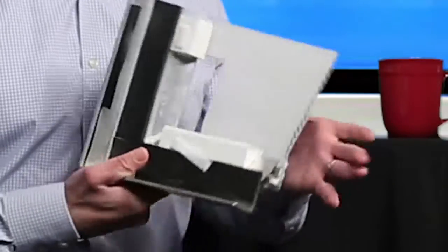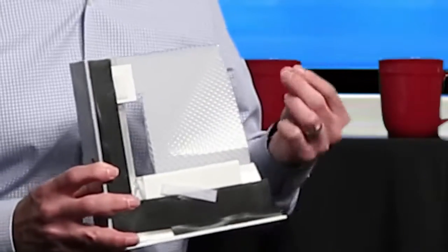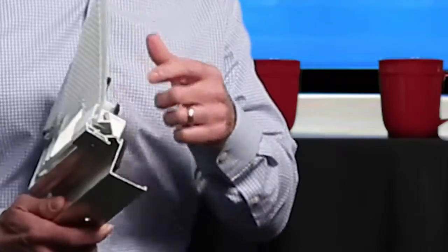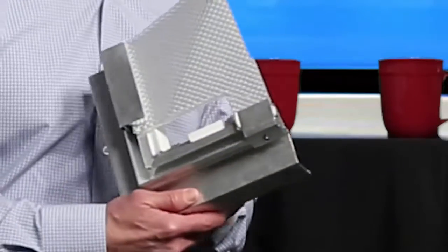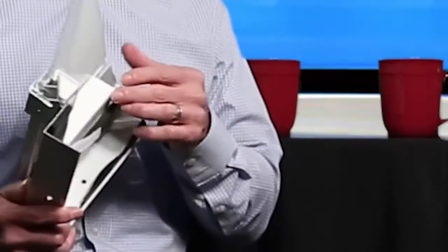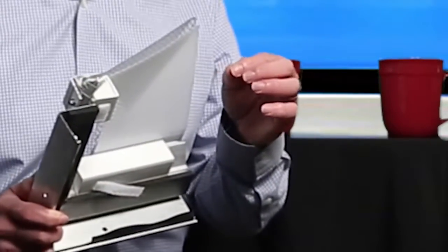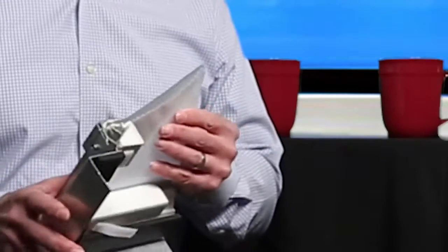And what we do here is that we have aspects to this frame to ensure that you get a very high quality skylight. Number one is we have a thermal break that we include here, if you can see that. See the thermal break? Yep. What that's going to do is reduce, or eliminate, the issues of condensation that you would have through the skylights. And that's important.